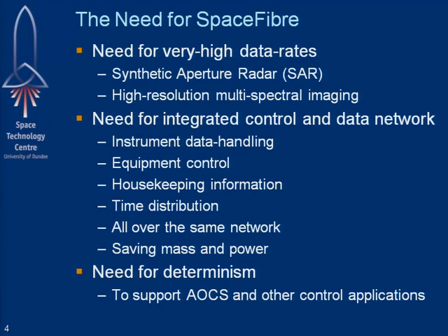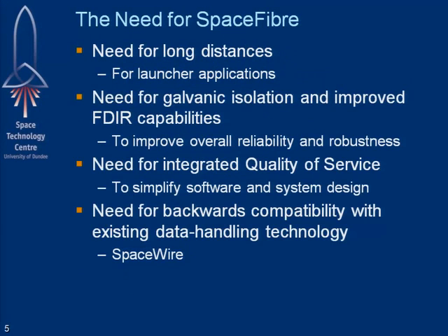But we also have a need for integrated control and data handling networks on board a spacecraft, where we can combine the instrument data handling that SpaceWire does, for example, with equipment control, housekeeping, gathering, time distribution, all over the same network, saving mass and power. We have a need for determinism for AOCS type applications and other control applications.